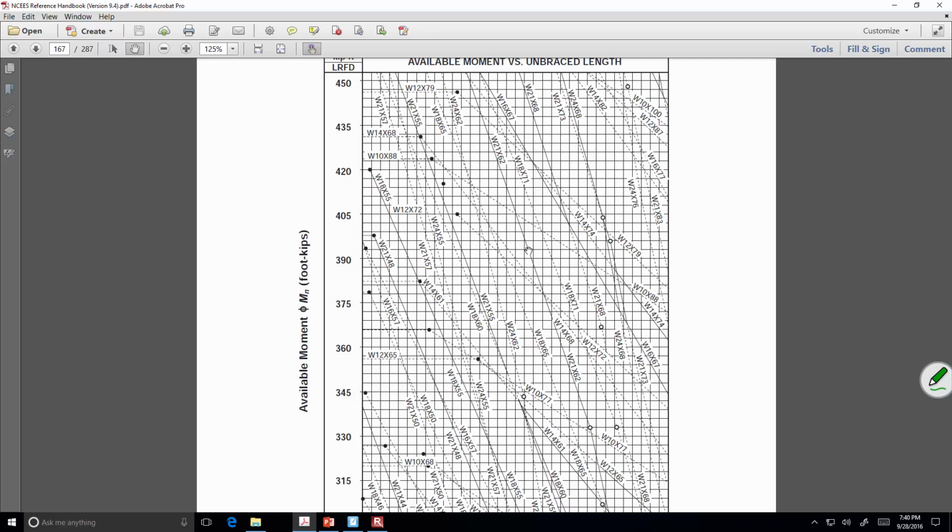All this whole time I've been talking about buckling. I've been talking about an idea called global buckling. In other words, the whole beam buckling. Make sense? What if the whole beam doesn't buckle? What if it's just the flange that buckles? The little plate, what if it buckles? Or just the web, okay? Well, no, it's not a matter of being screwed. It's a matter of now it's a whole different set of calculations, okay?